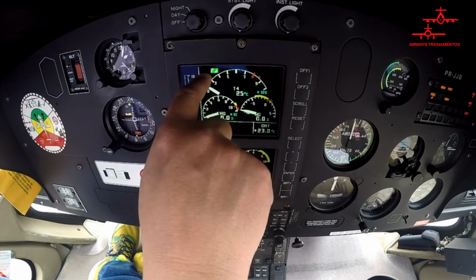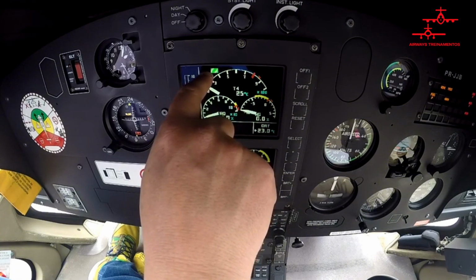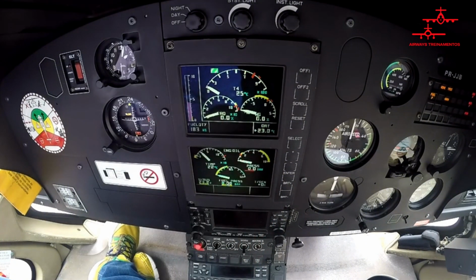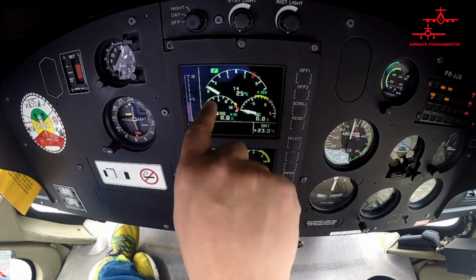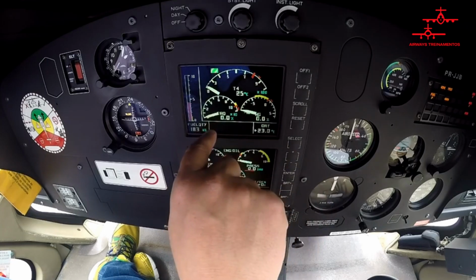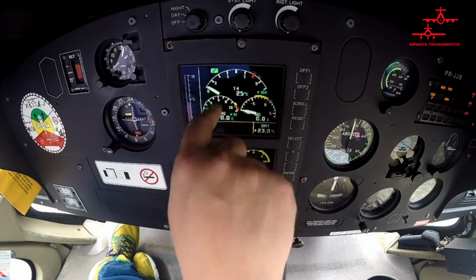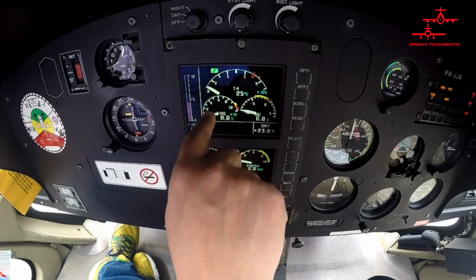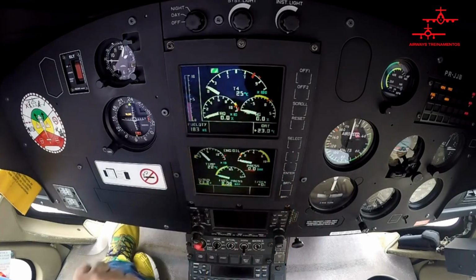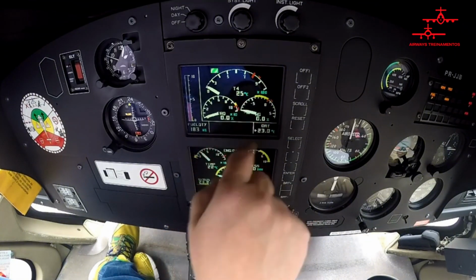And here, when the aircraft has a sand filter or when the heating is on, the so-called P2 appears here, which is the air bleed from station 2. We have the torque indication, which is being produced by the engine. The T4 indication produced by the engine. We have the torque indication and the NG indication. These indications at the bottom are also displayed as digital numbers.